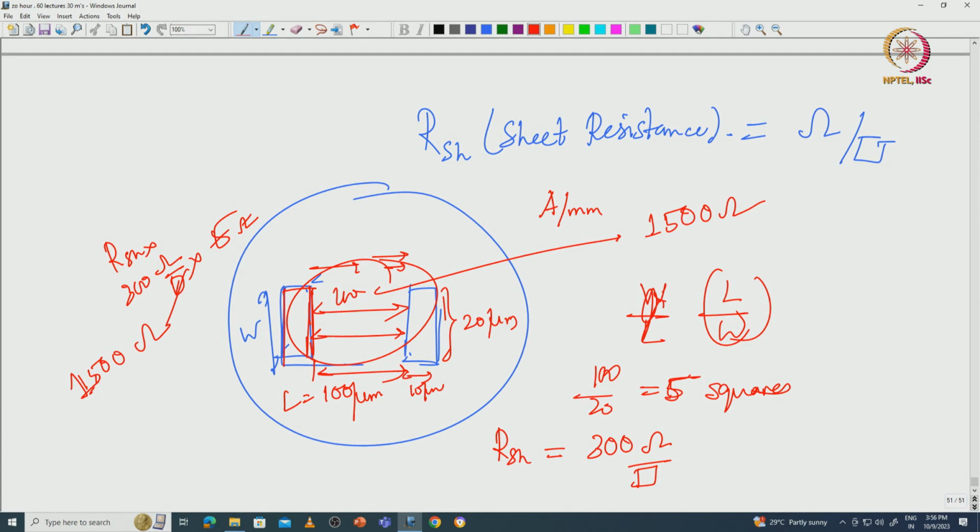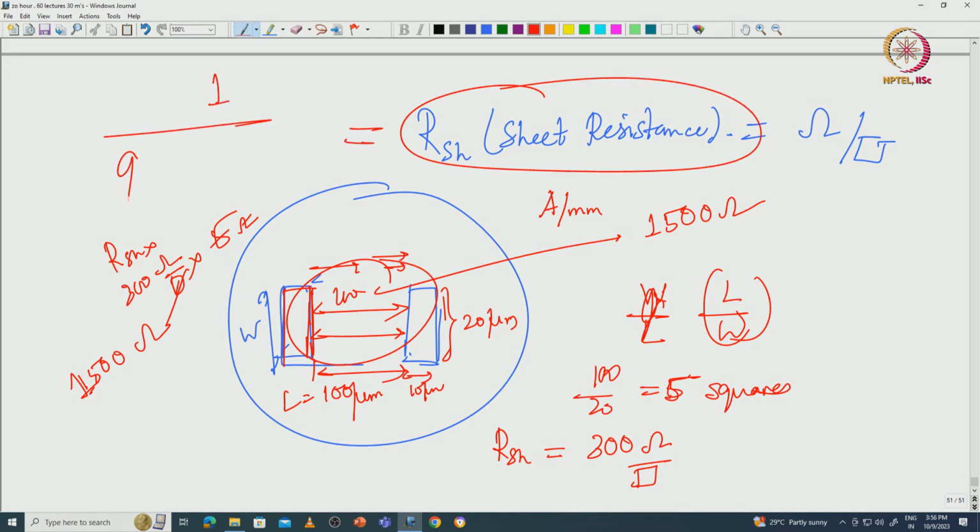So, the sheet resistance is a very important quantity, and this is given by 1 by charge of electron times the mobility times the 2D electron gas density. So, if you have a higher mobility and a higher 2D electron gas density, the sheet resistance becomes lower. It is desirable to have low sheet resistance because it helps reduce parasitic components. It also helps reduce the unnecessary parasitic resistance drops called the excess resistance, and it helps improve the overall on resistance of the device. Okay.